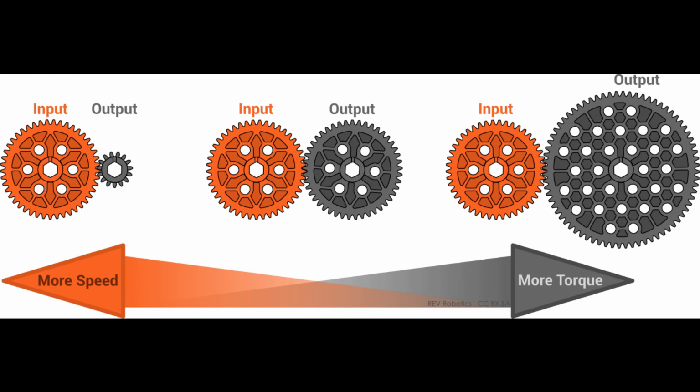But you can increase the speed that you spin a motor at by using gearing. So a high torque, low revving application can be matched to a high spinning motor by the use of a gearhead. It's not something that's very often done with wind turbines, for example. It's pretty common to bolt the blade straight onto the motor, and it's probably one of the worst things you can do if you're using the wrong kind of motor. What you want is a high torque motor. Of course, you suffer from that voltage drop that we saw. There are other things you can do with it, and we have been exploring some of those other things in the video.